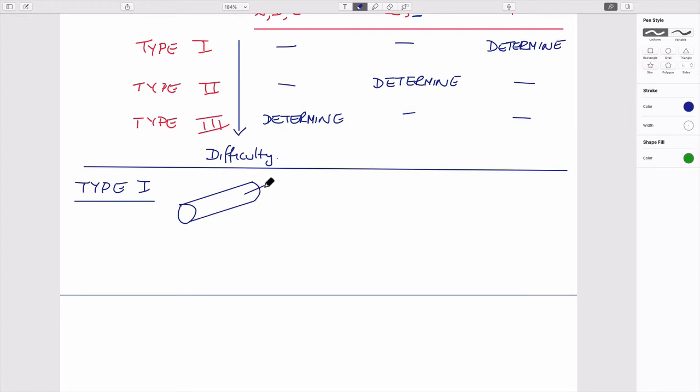And for that geometry, there'll be a flow velocity, there'll be a pipe diameter, there will be a viscosity and a density of the fluid. We'll choose water. I suppose we could have a relative roughness, which we could define. And I guess the other parameters we need to define are a length of the pipe